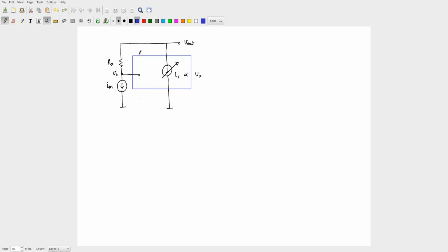It's a current controlled voltage source, so you can introduce a negative sign in the final expression that you want. In fact, we will do that when we analyze the full circuit. We will toggle the I in direction, because we usually want the current to go into the amplifier, so you will get a negative sign in the output.